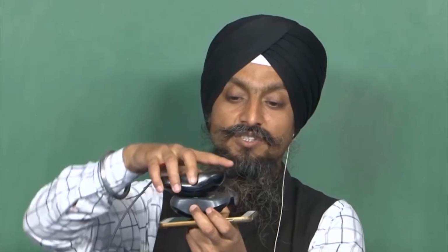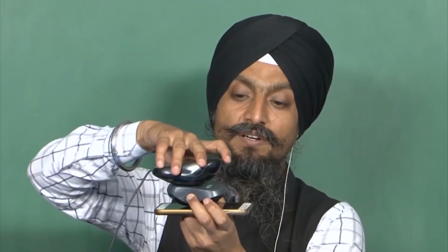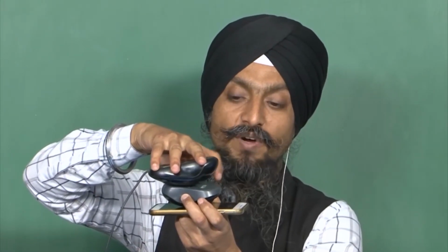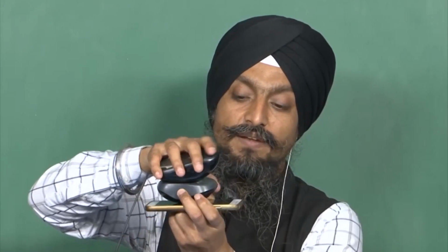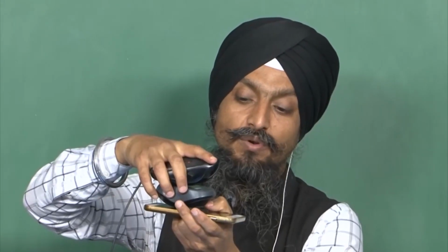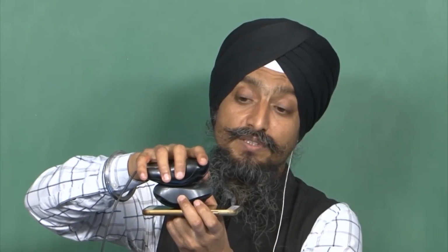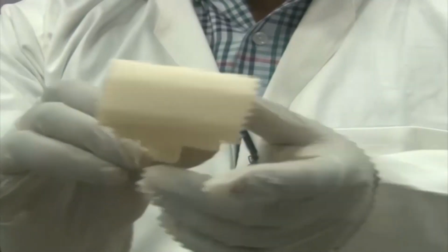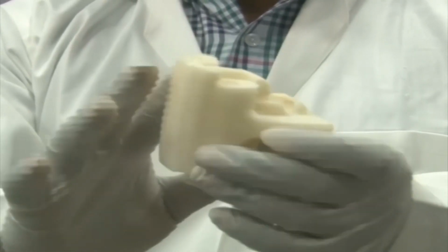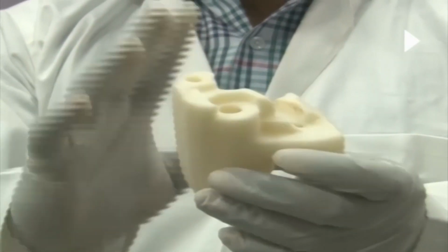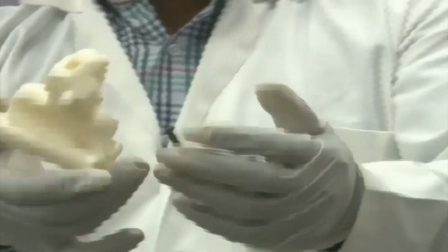If there is another model, for instance, another thing is manufactured here, the portion in between here is not touching the bed, but it would provide support here as well, because it has to produce this as well. So in case of touching bed, it will provide support here only. In case of everywhere, it will provide support here as well. So where it is complicated, we use the option everywhere. Now the software is responsible to fill the support wherever it is needed.